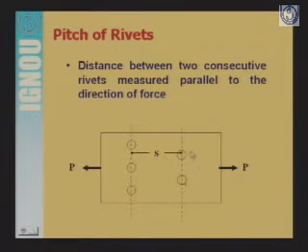These are rivets in two lines: 3 rivets in one line, 2 rivets in another line. This P is the force acting on this connection. So the distance we have to measure should be parallel to the force applied on the connection.